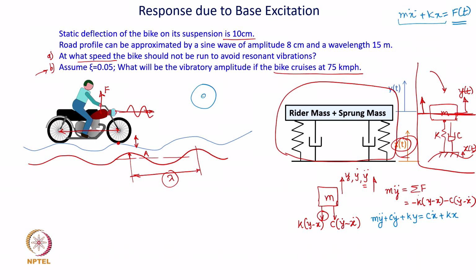Now, again let me go back to our rotor vibration problem. Was this excitation force, whose amplitude was m epsilon omega square, did it ever depend on the vibration amplitude r? It was a fixed value changing with only time. It does not depend whether the rotor whirls with r equal to 0, r equal to 1; even when r equal to 0, it will have the same value. So, whether r is 0, 1, 20, 30, 100, the excitation force is independent of the way the system responds or vibrates. So, the forces which are independent of the vibratory motion are external, it only depends on time.